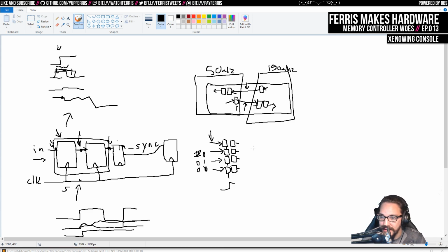So there's some really interesting things that they do where they actually only put these synchronizer chains on the control lines. So in this case, you would do this for the incoming clock. And then the data lines you just pass through. And essentially what you have here is these end up being sort of multi-cycle paths, because what will happen here, let's say you want the clock to be output here, and then you just have some registers here. I'm kind of showing this as time. So I don't think you do another register here. I think actually these should be aligned with these ones.